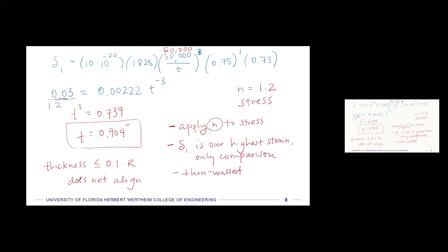So if the hoop stress is what's leading to the creep strain, that means the pressure vessel is stretching in the hoop direction, right, due to this creep strain. Then if our allowable creep strain is smaller, we have to have thicker walls to prevent it from doing that, to last the 5 years. And so that further violates some of our other assumptions.